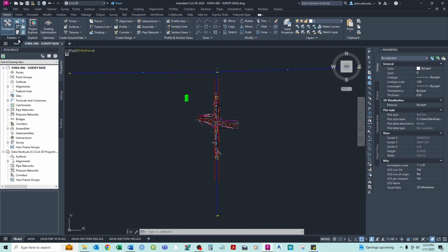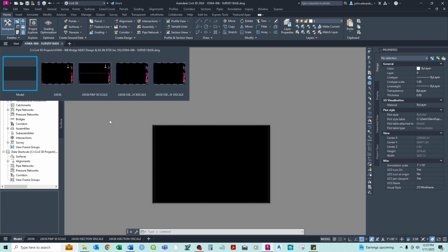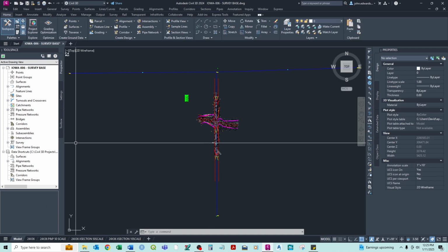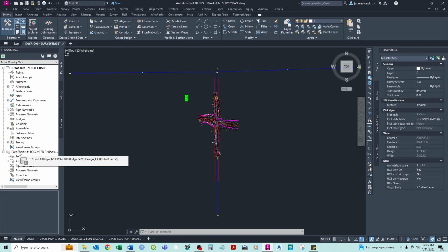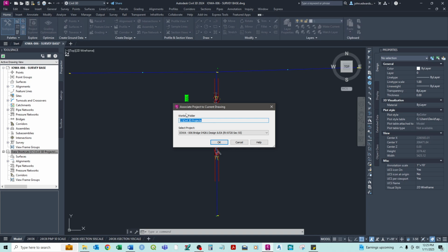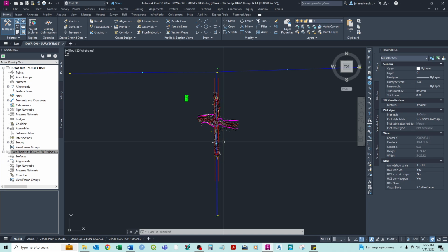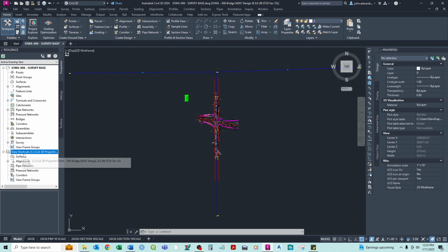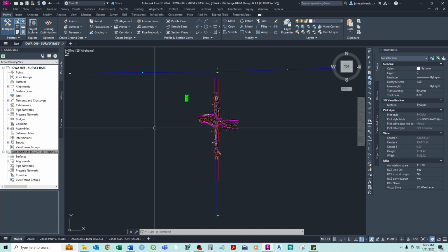Now, thinking about the fact that we just created a project that has a name, let's go down here that we talked about earlier and go ahead and associate this drawing essentially to that project. Okay, so again, our working folder, that's our Iowa 06 project. Good. So now essentially this project is referenced in that shortcut folder if we did create objects.